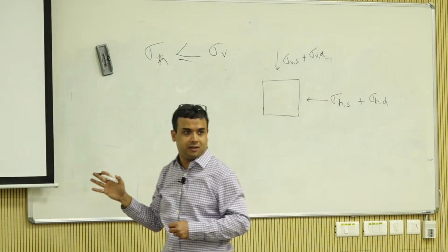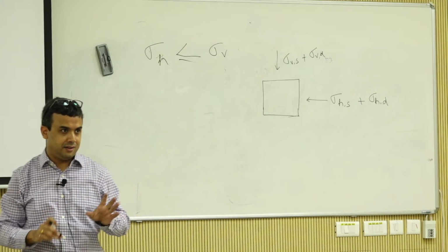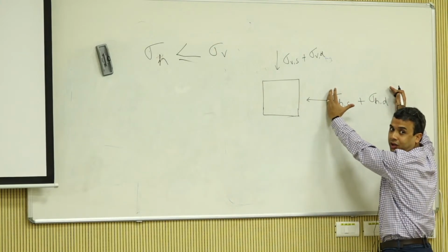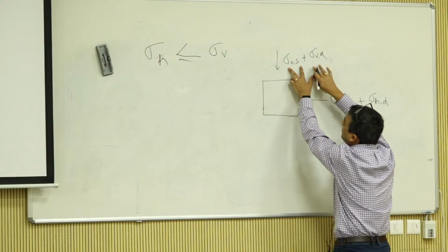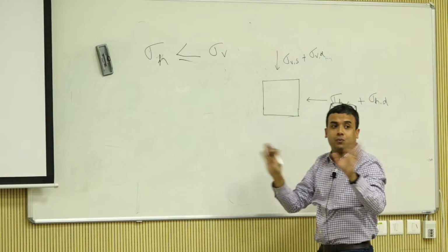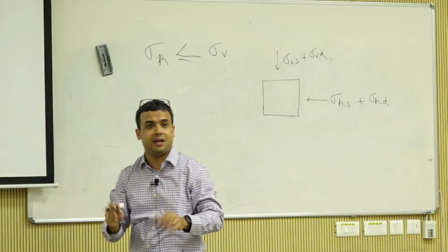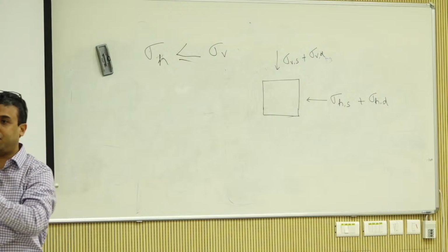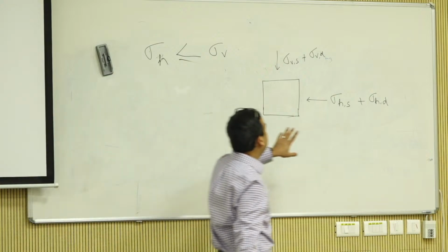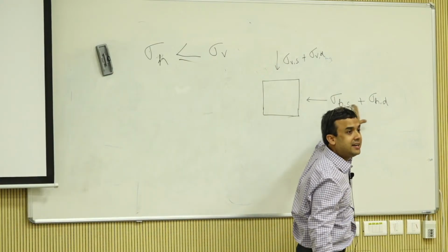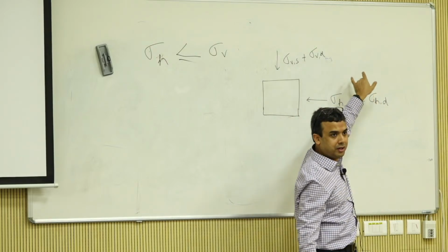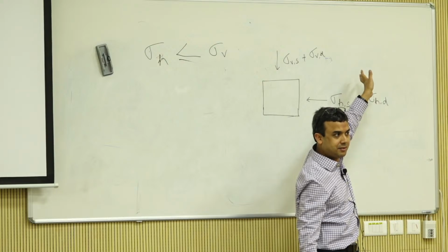Do you understand what I'm saying? Right? Until yesterday we were just talking about sigma h horizontal, and we still had sigma h or sigma 3 plus sigma d. Now I am not worrying about sigma 1, sigma 3 or anything. I am talking horizontal, vertical, pure separation, and I am saying some magical way I am going to say there is a static and a deviator component here, and a static and a deviator component here. Does that make sense?